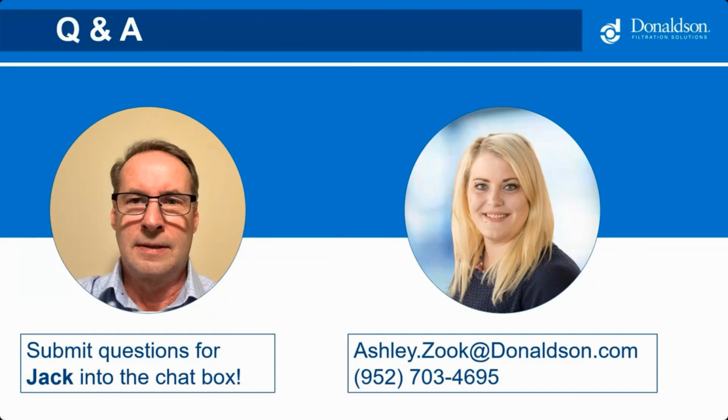Right. What are the design considerations for the angle of repose of baghouse hoppers? Okay, one more time, please. Okay, I assume they're referring to bridging, and if not, please respond back. So the concern is what type of material that you're collecting, and is it dropping out? Yes, you want to consider using potentially steep hoppers if the material is wet or is conglomerative.